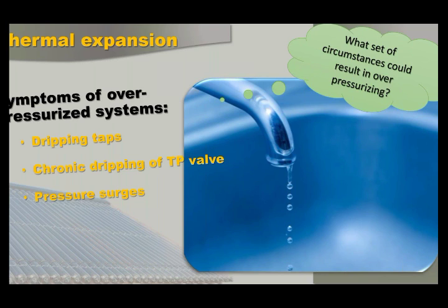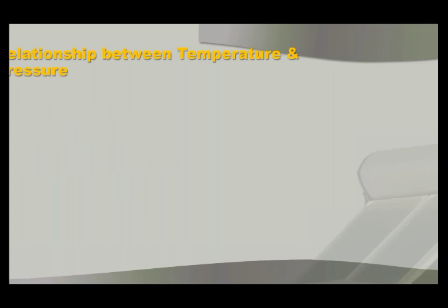So what circumstances could result in overpressurization? Well, you have a number of control valves that need to take care of it. As I said, the incoming side, the one that is supposed to do it, is a PRV. So if that's faulty, if your TMP is faulty, unbalanced systems and cross connections also can cause overpressurization. If you've got a cross connection and you have 1,000 kPa or 800 kPa of cold water all of a sudden rushing into your hot water system, it's going to do that.